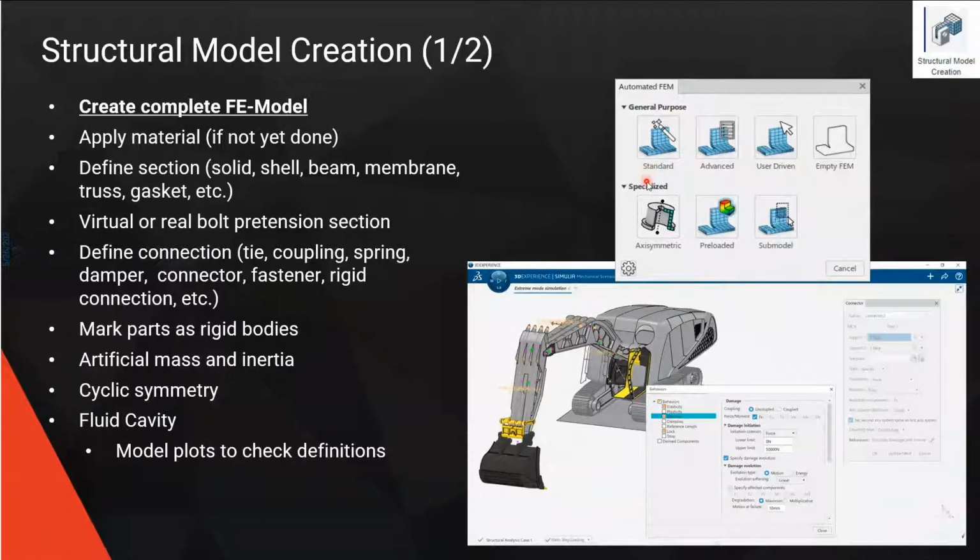Also, what to keep in mind is that the way the FEM is run in this analysis is great. You have an original part, and you take it in and create a FEM model of it, and that model becomes almost its own part. And you can make 10 FEM models and use them all if you want. So it's very modular. When you run a sim, you can choose which FEM model. You could have 10 different levels of mesh refinement on the body, and then decide, okay, I want to use the most coarse or the most fine or whatever you like for a given simulation. It's a really nice way of controlling it. Also the contacts are automatic, hassle-free, industry-leading, very powerful.